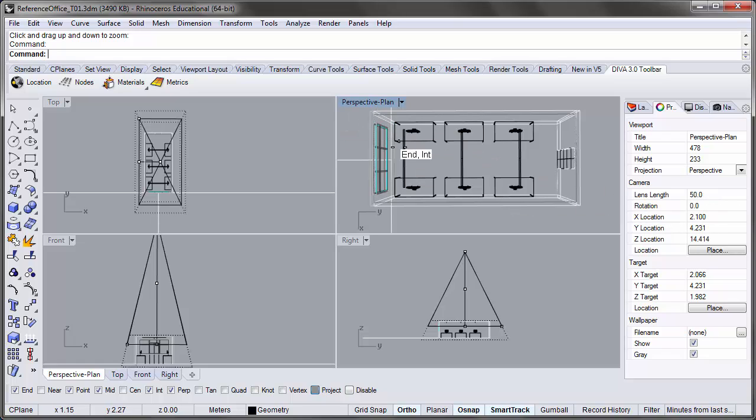As long as you started this view from, let's say, a perspective view and you rotated it into position, I think that should be okay. It's a little bit different if you start with the top view. The top view already has a kind of default rotation to it. If we were to change this to a perspective view and then ran our simulation, you'd get into some problems. So it's always good to start with a perspective view and then rotate it into position.